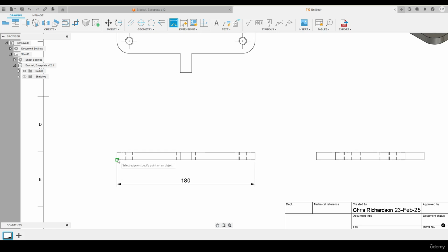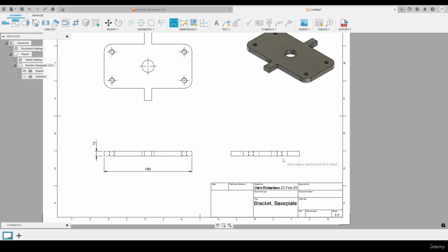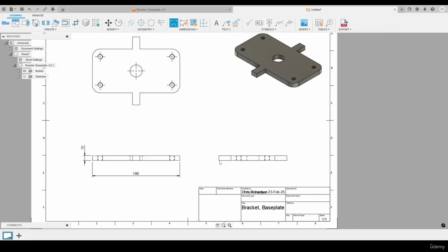Let's do the same for the extrusion height. So this point here to this point, put in the 10. Let's do the same as well for the total length from this corner to this corner. That is essentially the distance from this face to the corresponding opposite face over here. So this corner point, click here. And as we see in this dimension, there is 1 decimal place.